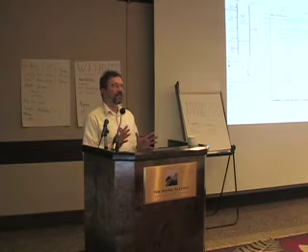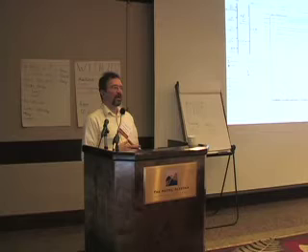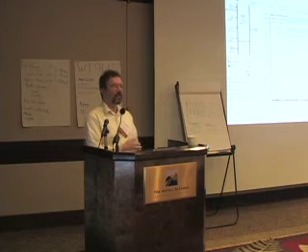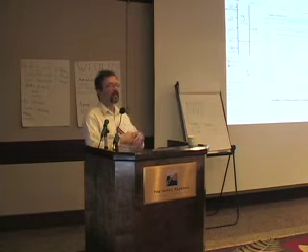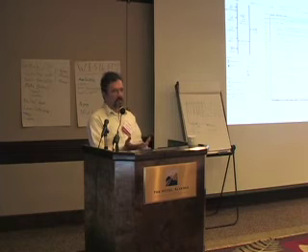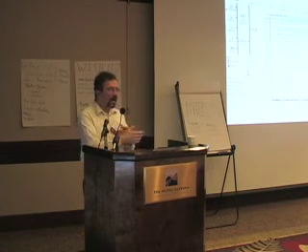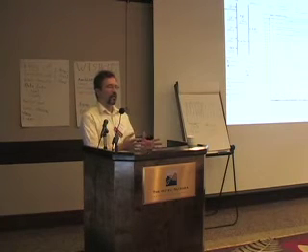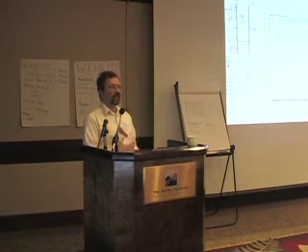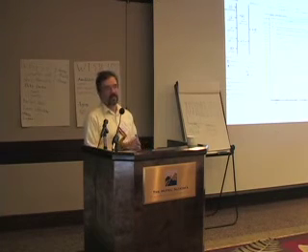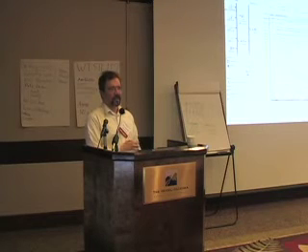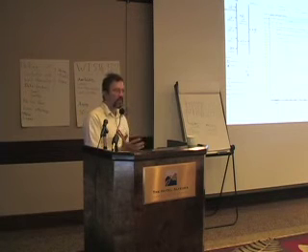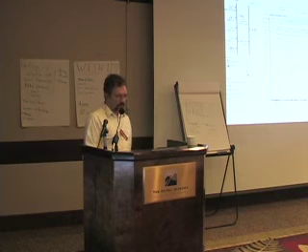I take that back. Homer calculates what's the cost of the energy that's in the battery based on what it cost to charge the battery. So that goes into this calculation, but it's typically the least cost way to meet the load. But there will be times, depending on your inputs, when you'll install a battery and Homer will never use it, because the energy that went into the battery was too expensive, and it was cheaper to not use it. That's kind of an unusual case, but it's all part of this. Homer's trying to figure out what's the least cost way to meet this load.